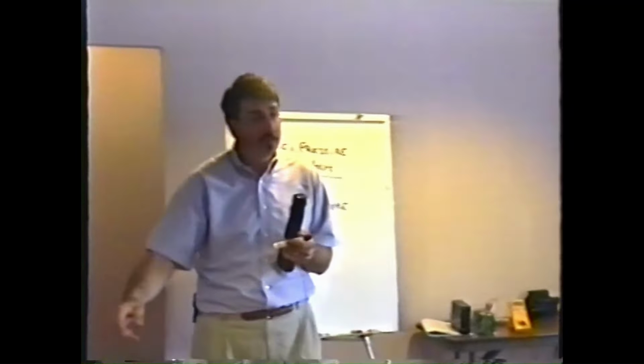When I draw ground in two or maybe even more different places, like, for instance, it not only goes to the radio, but there's also, I've got a CB rig, right? That side of that would also be grounded, right? That's the return path. The current flows into the radio, but current also flows into the CB. The return is back through ground.